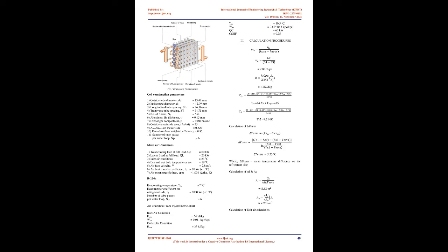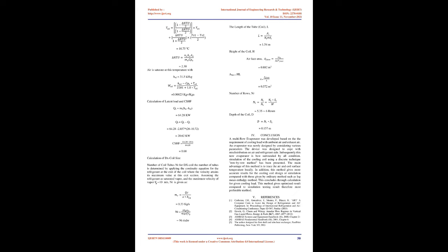Some coil manufacturers fabricate coils from 5/8 inch OD copper tubes, some from 1/2 inch copper tubes, and still others use 3/8 inch tubes. Selection of the tube size is a matter of manufacturer's choice and market demand. Price, as always, plays a major part in the tube size selection. In a coil, copper tubes are arranged parallel to one another, either in a staggered or non-staggered pattern, along the length L of the coil. A staggered pattern is more commonly used. For 1/2 inch tubes the spacing is 1.25 inch.